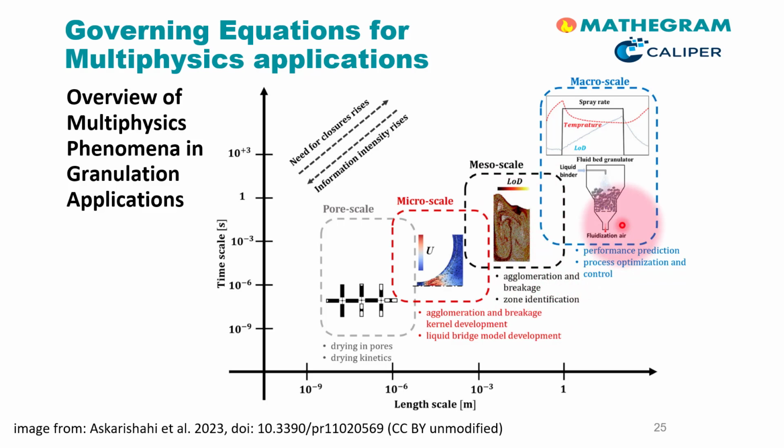The macroscale models are of great industrial importance since they aim at the prediction of the performance, e.g. of the drying rate in an industrial process. However, they do not involve fluid or particle flow simulations, since they must be very fast, e.g. to be able to evaluate them during the actual operation of a process. Such an on-the-fly process simulation is needed since macroscale models are sometimes used in the control of a process.